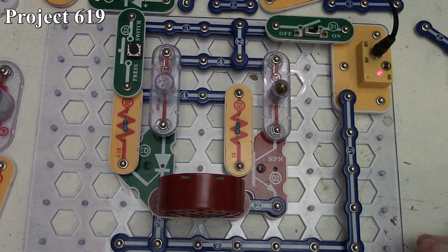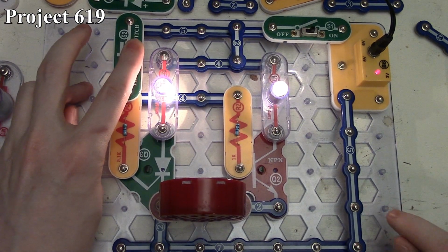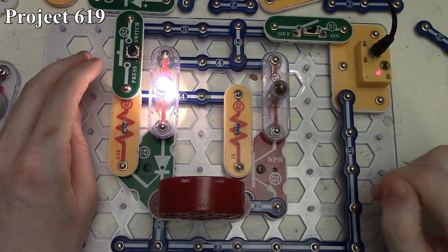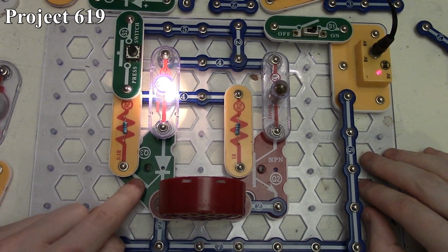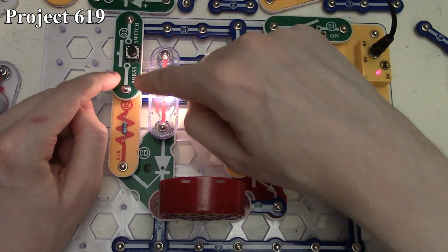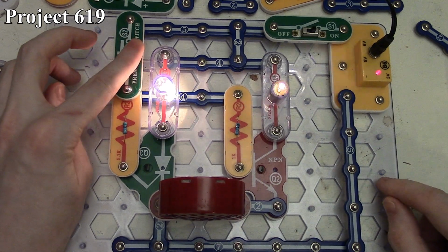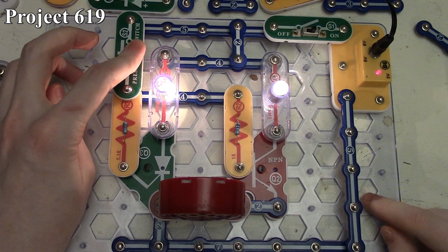Then when we turn on the circuit, obviously nothing happens until we press the press switch. When we press the press switch and hold it down, both our 6-volt lamp and 3-volt lamp light up. But when I release the press switch, the 3-volt lamp here goes out, but our 6-volt lamp stays on. And that's because we've triggered the SCR, so our 6-volt lamp stays on, but without a continuous supply to our NPN transistor's base here, our 3-volt lamp here will not light up until we hold down the button. And then that provides a feed to our NPN transistor.